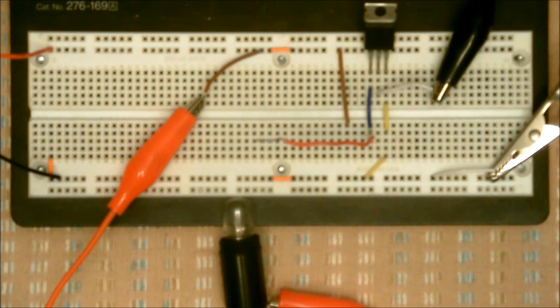That means that this transistor requires a charge to turn it on. This is known as enhancement mode. Depletion mode refers to a transistor that is already on, but needs a charge to turn it off. For the N-channel enhancement MOSFETs, you require a positive charge to turn the transistor on.